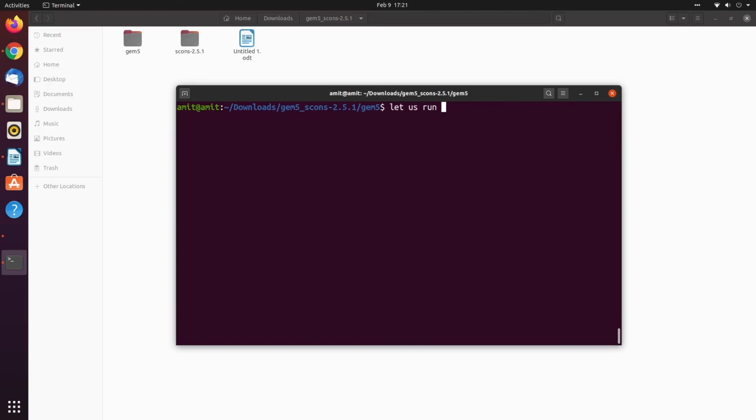So now let us try to run a workload on our simulated alpha architecture. We have a set of workloads inside the binaries directory, which is inside the gem5 directory. These workloads are basically CPU 2006 benchmarks which can be used to measure the performance of our simulated architecture. Here we will try to execute one benchmark using the command build/ALPHA/gem5.opt.